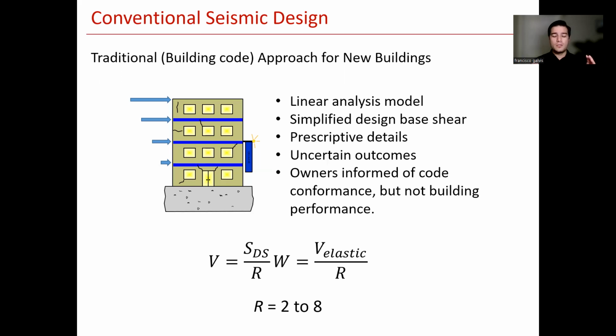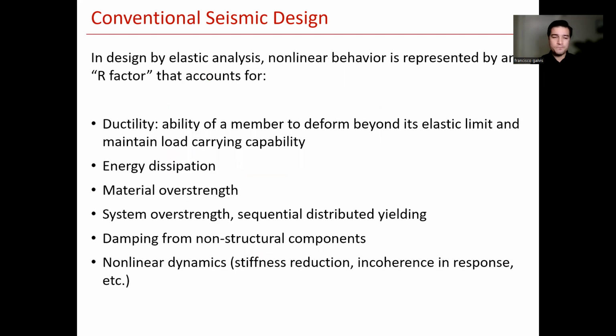That's the concept. So all of the performance that building codes for seismic design are built upon is on saving lives, not saving patrimony. So damages during the design earthquake would be really high and potentially demolition is required.